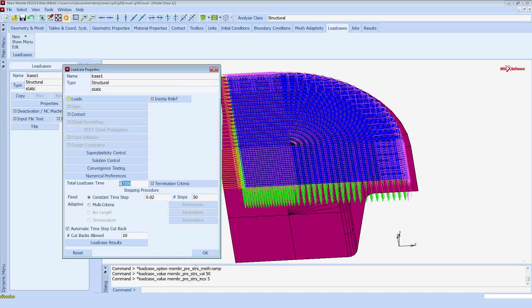And I am specifying 7200. It means, once again, it is a maximum value, so the physical process doesn't run more than 2 hours. And we do expect the whole forming operation to complete before 2 hours. So that's why we specify that number.